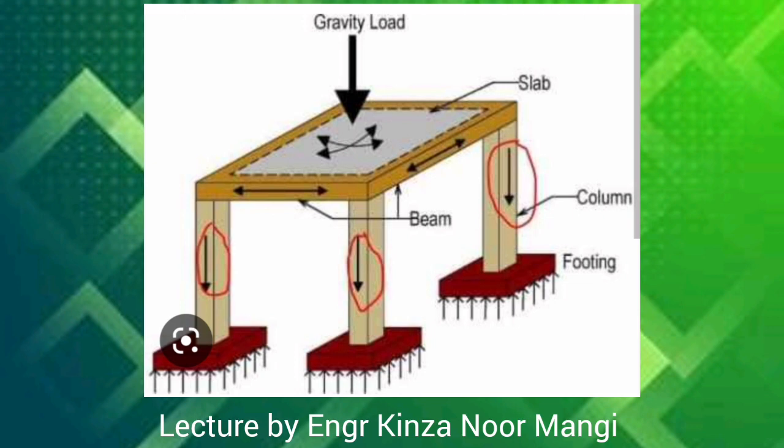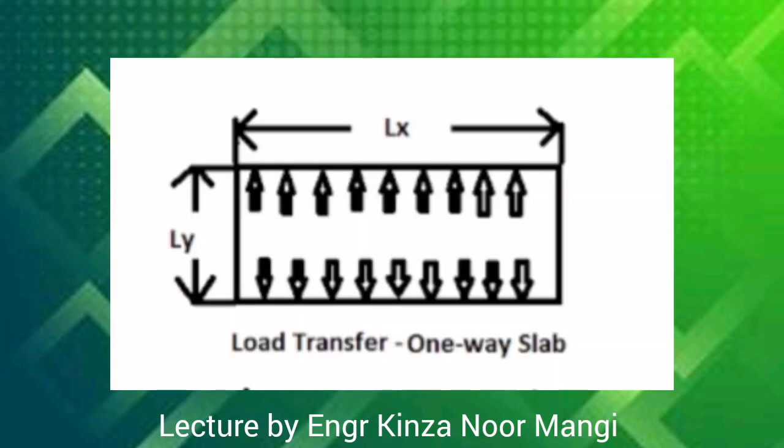The transfer of loads from a slab to beams is controlled by the slab's geometrical dimension and the direction of reinforcements. The load of the slab, including self-weight, live load, and imposed dead load, are distributed over the beams on their sides. The slab loads are expressed in weight per unit area, whereas loads of the beams are expressed in units of the weight per length of the beam. If the slab has regular dimensions, the load transfer can be carried out easily and quickly.